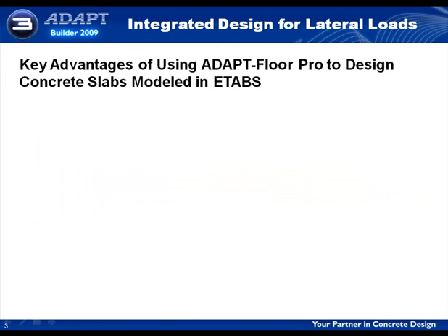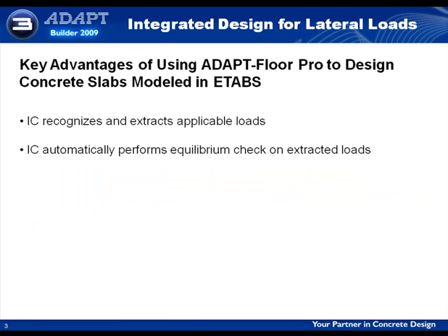The demo has ended, and we will now conclude this video by reviewing the key advantages of using AdaptFloor Pro to design concrete slabs modeled in ETABS. The first key advantage is that the integration console recognizes and extracts applicable loads. The integration console also automatically performs an equilibrium check on the extracted loads. If the equilibrium check passes, we continue in our design process. However, if needed, there's an algorithm that can redistribute the errors from the ETABS model.